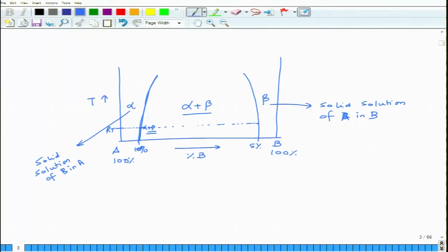If you know the phase diagrams, the proportion of alpha and beta will change in this regime, but you will have two phase coexistence because the solid solubility of alpha and beta are limited. So, this is the limit of solid solubility of beta, this is the limit of solid solubility of alpha, and this happens when you have departures from Hume-Rothery rules, when the size differences are larger, when crystal structures are not similar, when valences are not similar, and when electronegativity difference typically gives rise to formation of compound, but these are the factors.